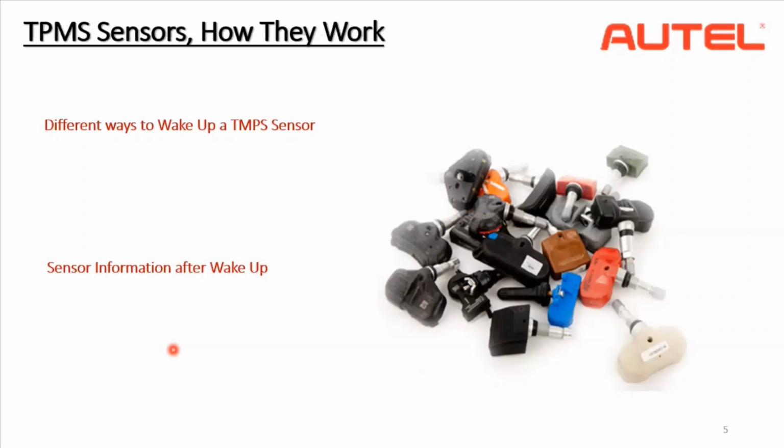Now I'll tell you the different ways to wake up a TPMS sensor or get it active for us to retrieve the data from it. The first one is loss of tire pressure. As I told you before, if there is a pressure difference of 25% up or down, then the TPMS warning lamp would come up, the sensor would be activated, and it will send a signal through the antenna to the vehicle's ECU and give you the warning lamp for TPMS.